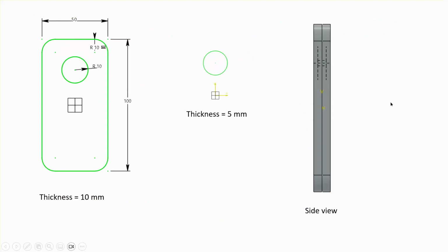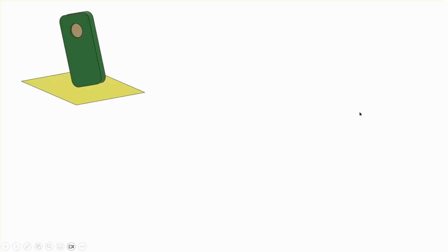Okay, so the dimensions are given here, and when I drop this initially, I make sure that when it hits the analytical rigid surface down here, it hits it on a line, which means there's an initial line contact. Then I will also come back and tilt this analytical rigid surface a little bit, so that when the camera is dropped, it will hit it at a point. And because it's hit on a point, it kind of wobbles around.